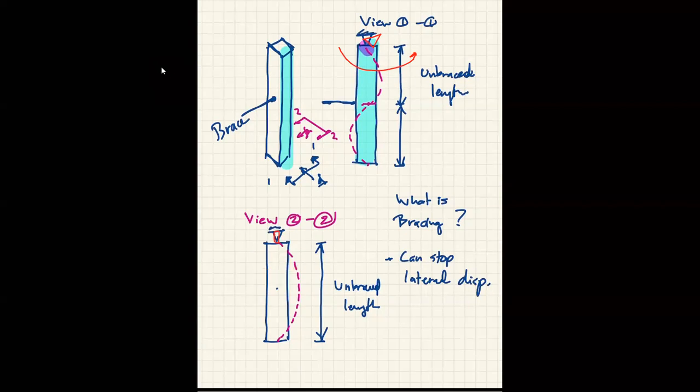If you give the symbol like that, it means your structure can rotate. To have a pin in the real world can be difficult, but it depends on the condition of your structure. You must consider both axes and see if both directions are pinned.